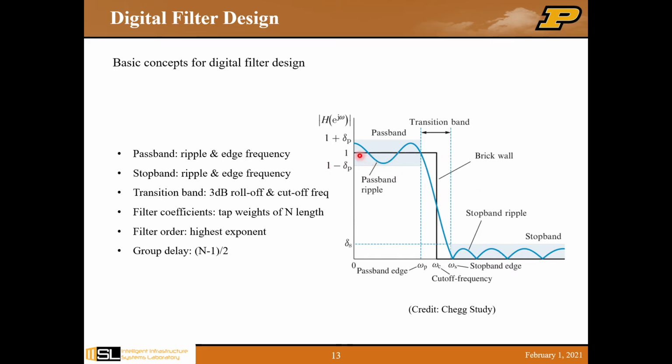The black curve, the square step signal here, represents the idealized low-pass filter. However, we can never realize this ideal low-pass filter. Instead, we can only approximate this behavior. So the blue curve is a typical filter response in the frequency domain.